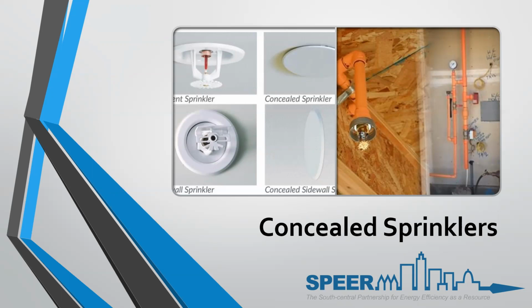Or, as you see in here, you can make all of them a wall sprinkler, which now you just have to air seal the pipe coming through the top plate. And now it doesn't have to be sealed at the sprinkler can. But that always goes back to it intersects energy and fire code. Fire code will always win out with its health and safety.